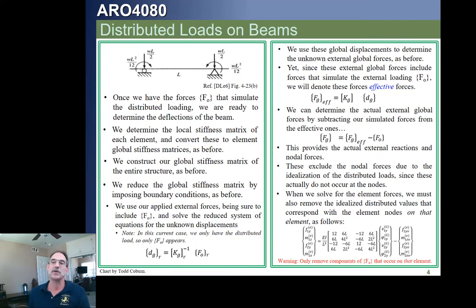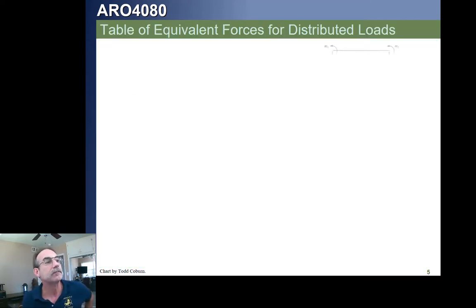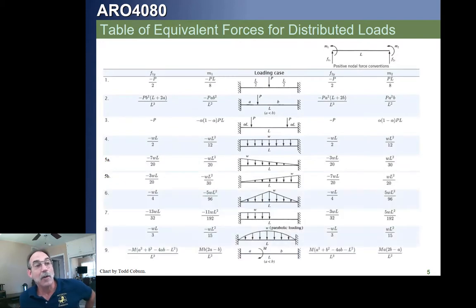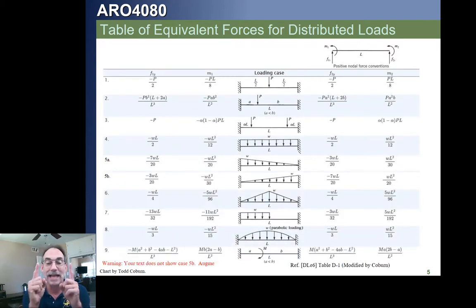That's how we're going to tweak our procedure. All right. Now, that was for a distributed load on a beam. Remember, we're just talking any beam element. We use the fixed case because any beam that's continuous, that's attached to other structure, has the potential to transmit that moment.